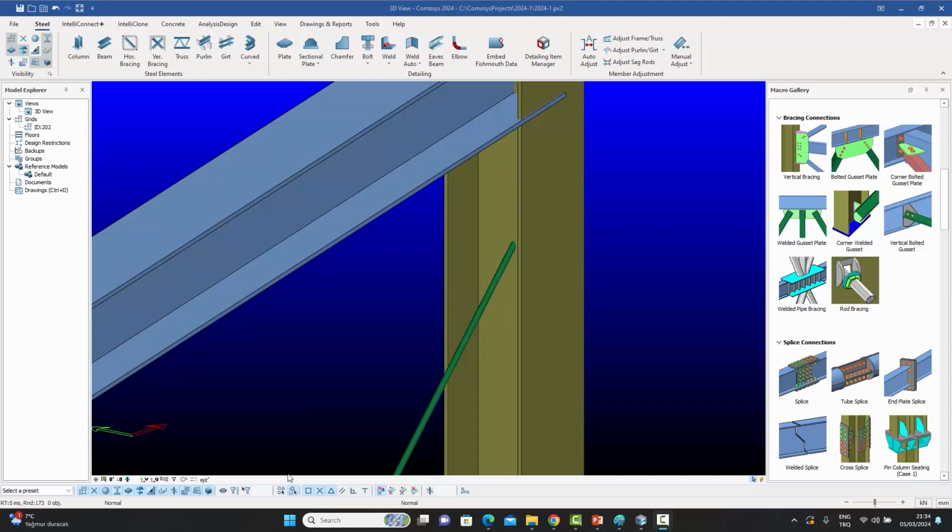Now let's consider this situation. This is the fourth macro which we've developed for you in this version. Usually, whenever we have significant seismic forces or significant wind forces, you never do something like this. You don't use these flimsy rod profiles as your bracing. But when your loads are really low and all you need to do is make the structure stable, taking a little bit of load, then it is common practice to use these rods as bracings. And in those cases, obviously, you want a simple connection, and some standardized equipment is also used.